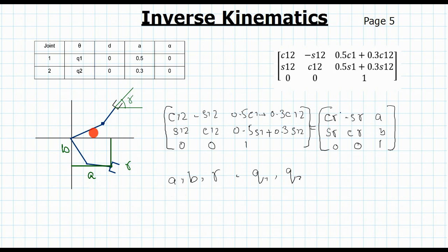We can use these 2 degrees of freedom to set the values of A and B, but we cannot use them to also decide on the gamma that we want. The gamma is decided once we set A and B. If we want a robot that can achieve any A and B and gamma also, then what we need is another degree of freedom. We can maybe add another joint, a link, or maybe we don't even necessarily need another link. We can just add one rotation here.